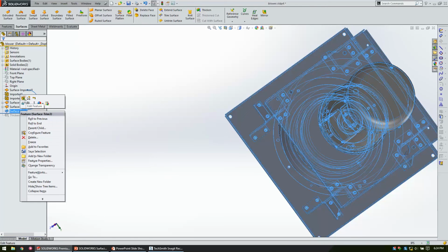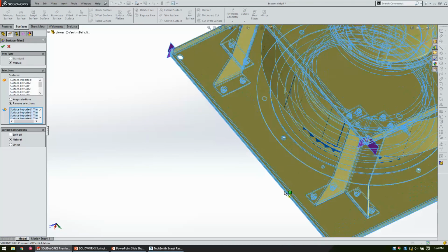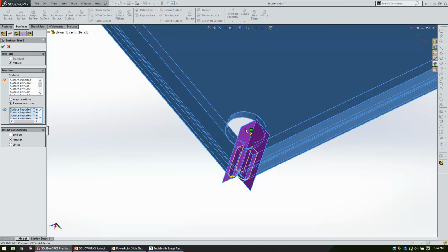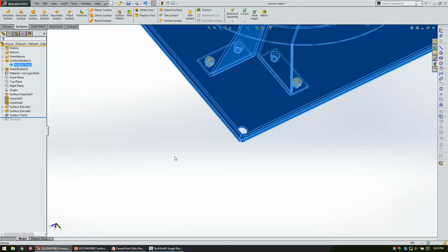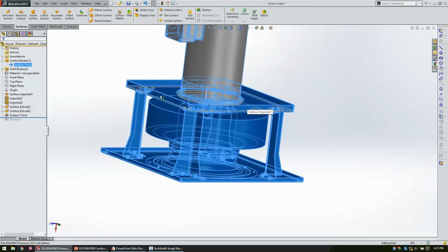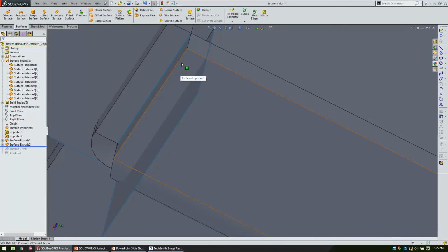You can see how long some of the surfacing stuff takes to think. It's kind of a bear. So they basically drew 4 of these little things on all 4 corners and tried to do it, and it still wouldn't work because, without realizing it immediately, this entire thing is one huge surface model, which means it was also trying to knit these corners, which were also touching.